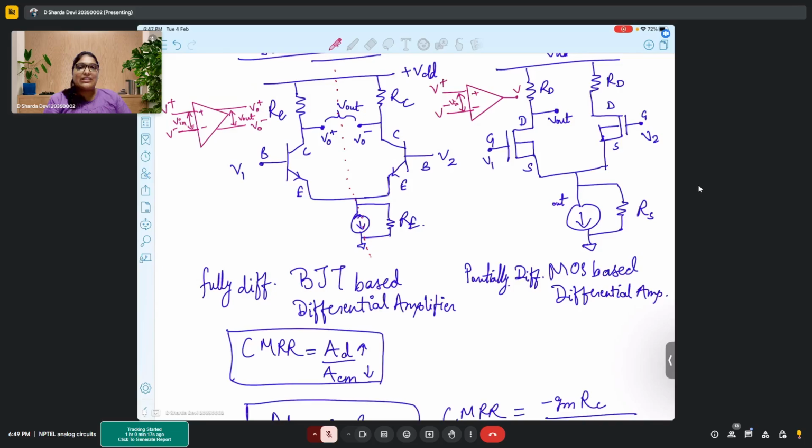If I talk from the transistor working point of view, let's say one transistor is a little faster than the other. Reaction times are a little different, and if the resistance values are a little different, all these lead to behaviors because of which you would have V naught plus and V naught minus slightly different from one another, which gives you the ACM's corresponding output. Because if everything was the same in both circuits, you can see that V naught plus will always equal V naught minus. There is no way you would get V naught plus not equal to V naught minus, because the circuit is symmetric.